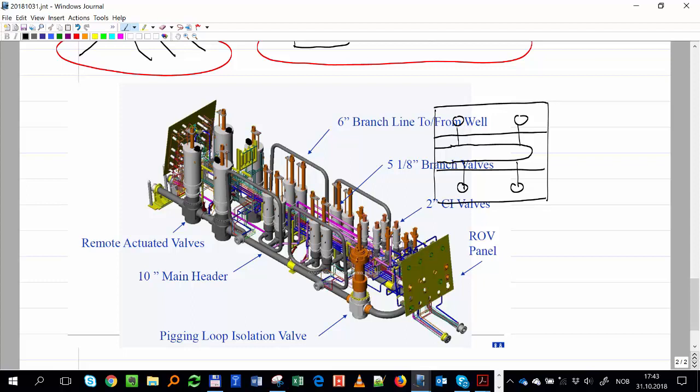So it takes space, but the thing is that if you have a rigid piece of pipe and then you're going up, it's going to break or it's going to fatigue. If you have a coil like that, then when it goes up, it's just going to bend a little bit. It's more flexible than having just a straight piece of pipe.